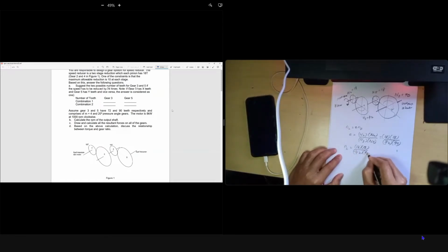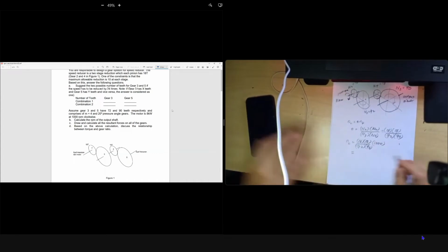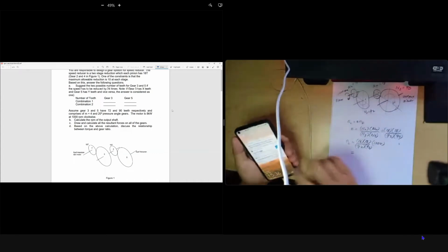So what do we have? N last is 18 times 18 over 72 times 90 times N first, which is 1000 RPM. What is the answer, class?